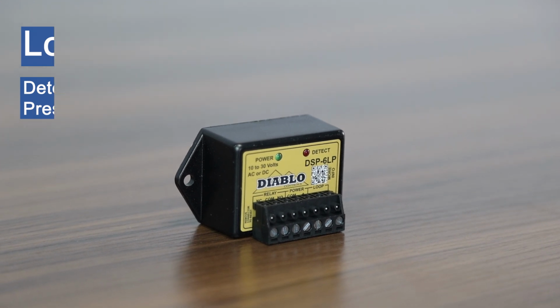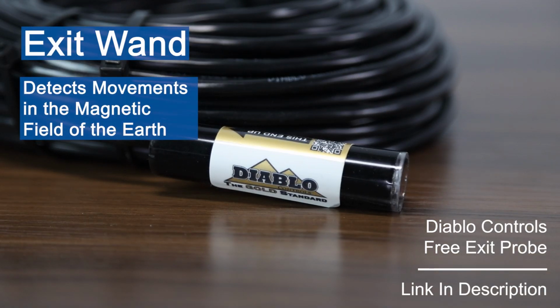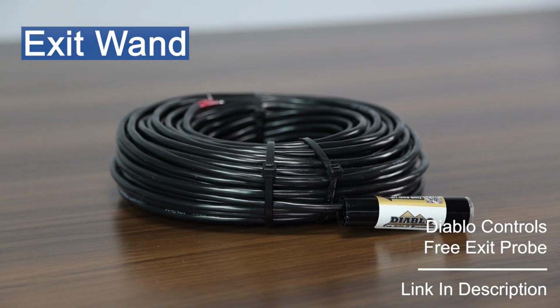Specifically, the safety loop detects the presence of metal, which the loop detector then tells the gate opener system that a vehicle is present. An exit wand or exit probe is similar, but instead relies on detecting movements in the magnetic field of the Earth. This differs from safety loops because it loses sight of the vehicle when it stops moving, but it still works great as a way to allow automatic entry and exit.